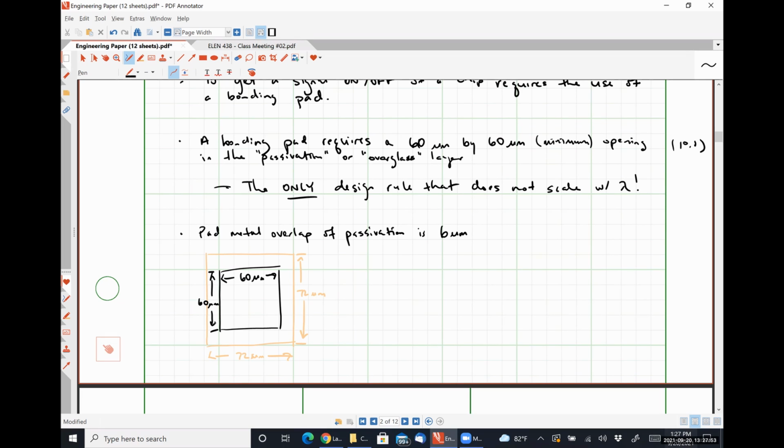So you always have to remember when you're designing your bonding pads that the 72 micron by 72 micron is the absolute minimum. Chances are they're going to be larger than that, depending on how many you need and the size, space, and all that. I would argue that you want to make them larger than the minimum size if at all possible, because that is your access to the chip from our scale of stuff, okay?